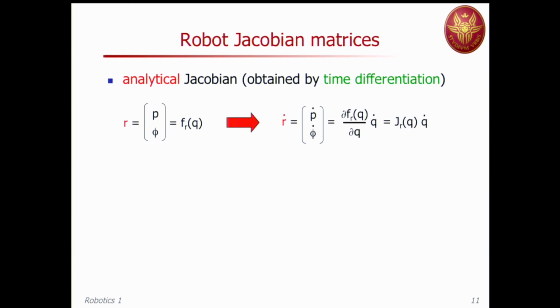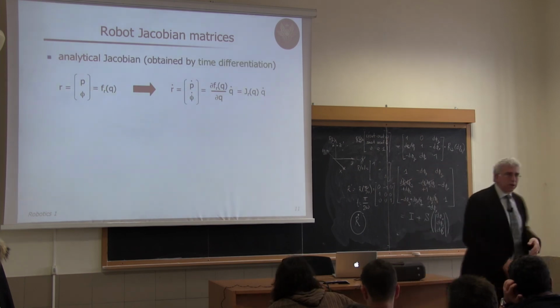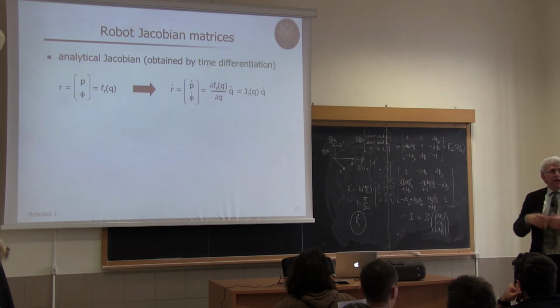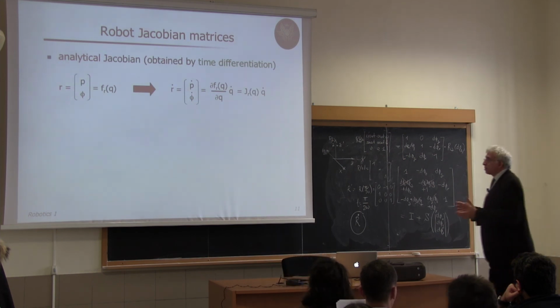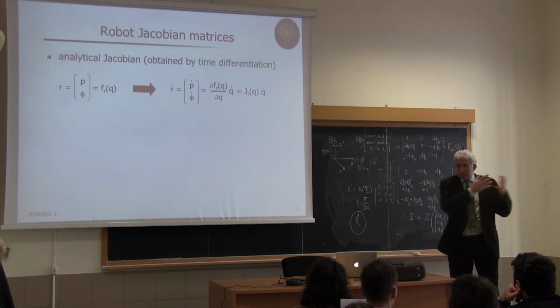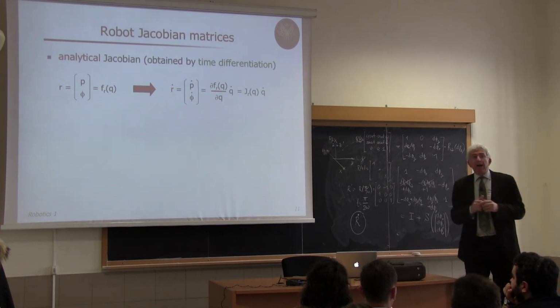Now let's become operative. Okay, we have mentioned that what we have said was just representation of angular quantities and mapping between omega, r dot, alpha dot, beta dot, gamma dot, and so on. Now we want to go back to the manipulator and compute the mapping between joint velocity and effector velocities, whatever they are.